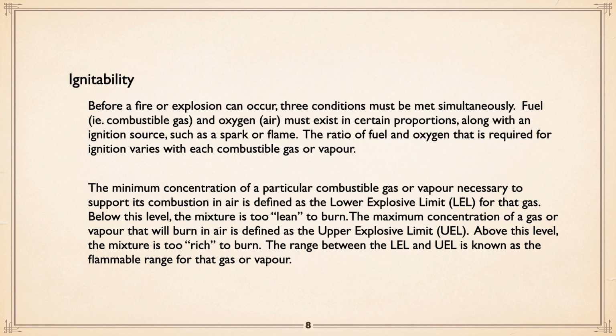That rate and proportions we will come to in a minute. The ratio of fuel and oxygen that is required varies with each combustible gas or vapor. The minimum concentration of a particular combustible gas or vapor is defined as the lower explosive limit. In other words, you have to have a certain amount of that hazardous gas to get it to explode.